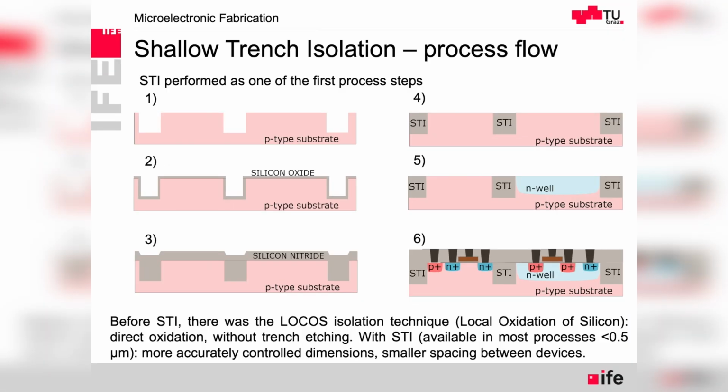So this is how such shallow trench isolation process flow goes. We have predefined where the transistors will be placed. And it's not very self-aligned like the gate self-aligning technology that you might recall. But everywhere where we know it's not going to be a transistor, it's not going to be a polyresistor or diffusion resistor, because this P+ region or the polysilicon we can also use as a resistor since they have certain defined and low resistance, then all those remaining places we fill in with STI, the insulation.